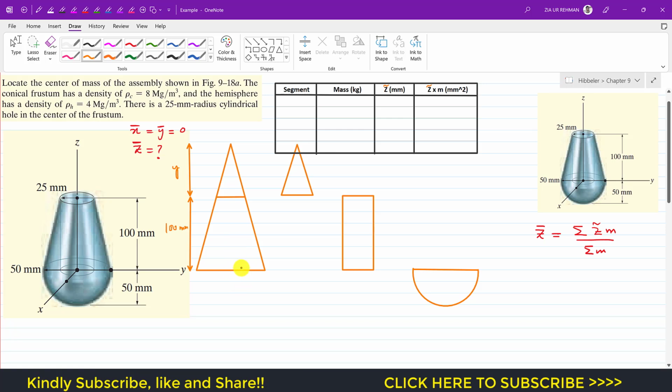And as we know, here the radius is 50 mm. If I draw another line here, this is the cross section of that cone, that cone is a 3D cone, remember. So this radius is 50 mm, this radius is 50 and this radius is 25. This is given. So this height is y and this height is 100 mm. So these two triangles, this triangle and this triangle, are similar triangles. So we can apply the properties of similar triangles.